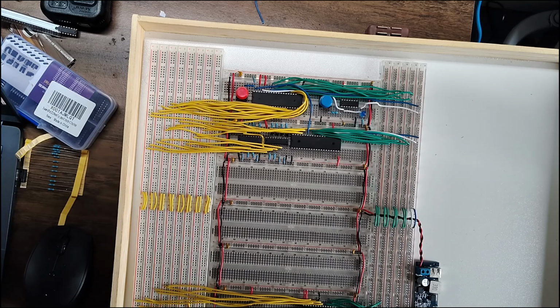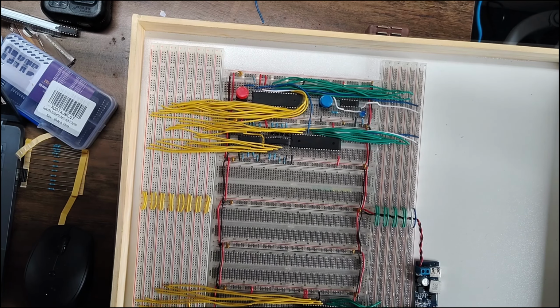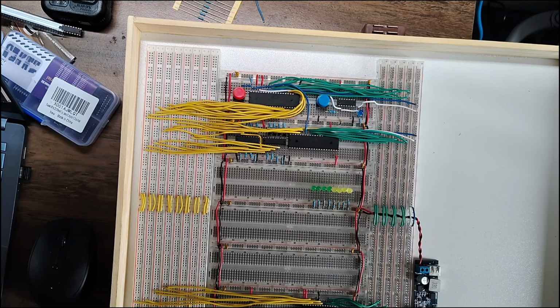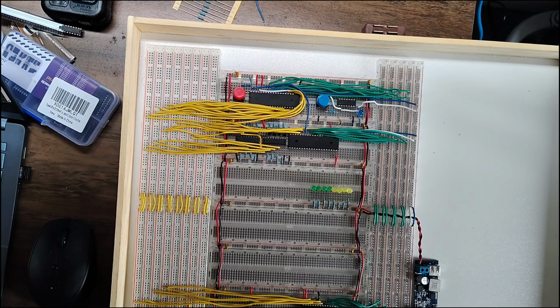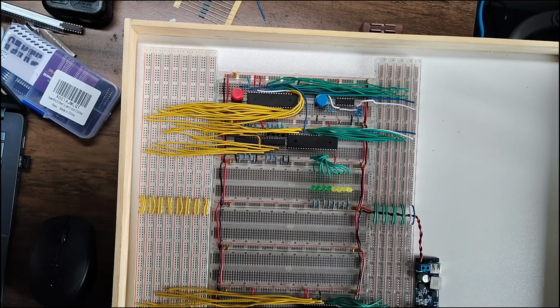So what I can do is I can get some LEDs and some current limiting resistors like we did in earlier episodes, like this, and we connect it to one of the ports, for the sake of argument, port B, like this. Then what we have got is a device capable of outputting to these 8 LEDs. Now, okay, I grant you that 8 LEDs, if you're used to a screen with 12 million pixels, is maybe a little bit on the low side, but it is a start.